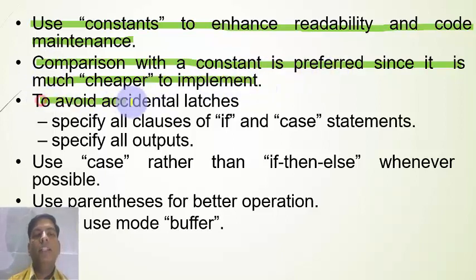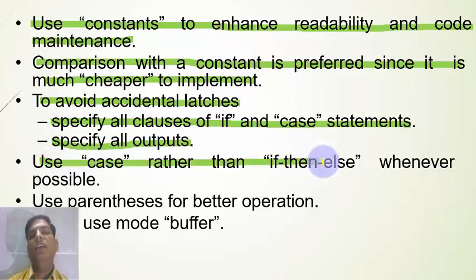To avoid accidental latches, specify all clauses of if and case statements. Specify all outputs. Use a case statement rather than if-then-else whenever possible. Use parentheses for better operation. Never use mode buffer.